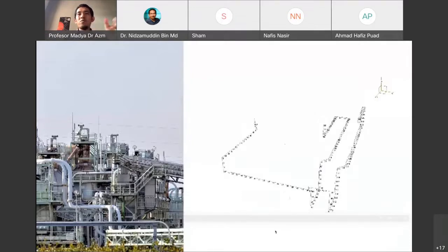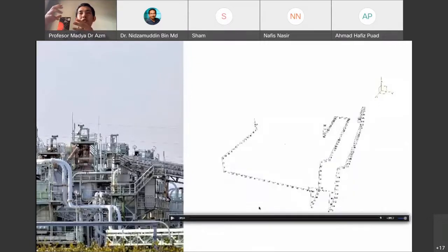We don't have to perform contact measurement, so it is a bit safer compared to coming very close to the pipe, where we should put the H2S gas detector all the time. If there is a leak of H2S, we have to immediately leave the plant. So with this new technology, we can have a safer kind of measurement.